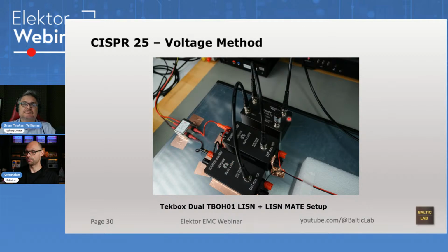And now I have two outputs, differential mode and common mode. I hope everyone's familiar with common mode and differential mode, but a very brief recap: differential mode signals, the way we usually know them and learn them in school and university, travel in opposite directions. Like here, you'd have the positive supply going that way and coming back that way.